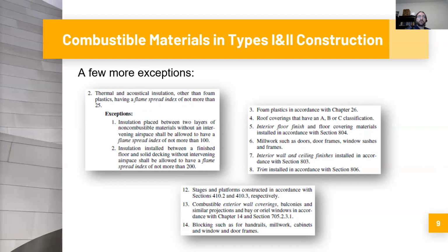That's different than the actual wall structure itself, meaning you can have a non-combustible wall structure, and in some cases you can have a combustible cladding. Think of something like a steel stud exterior wall, a steel framed wall that happens to have some wood siding on it. In that case, the more important element is the actual frame, the structural frame of the wall, meaning the studs.